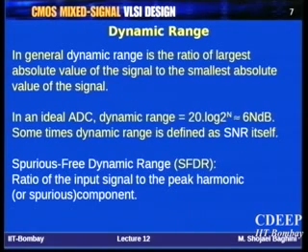Because you don't deal with signals whose magnitude is below LSB size, right? Your resolution is limited, you cannot detect signals which are less than 1 LSB within some range. At any center point, you have this resolution of 1 LSB. Therefore, the minimum signal you can actually detect, if you start from 0, will be just the LSB itself, starting from the first bit, the LSB bit. So, sometimes SNR itself is used as a definition of dynamic range. In some literature, you may find it. Therefore, know that this is the same thing.